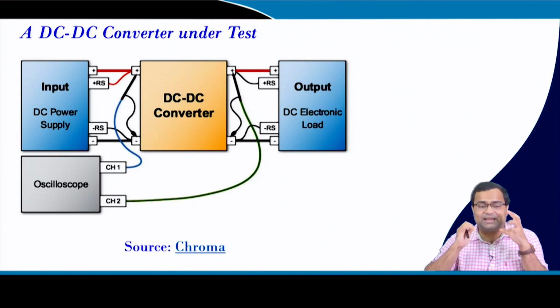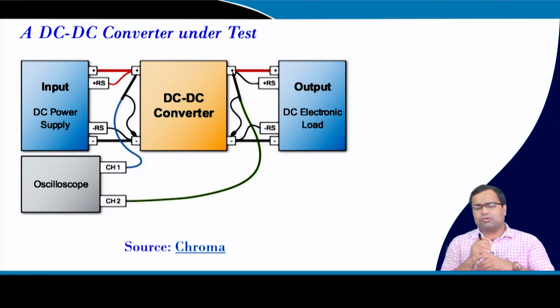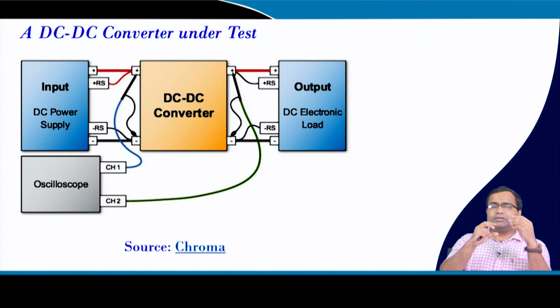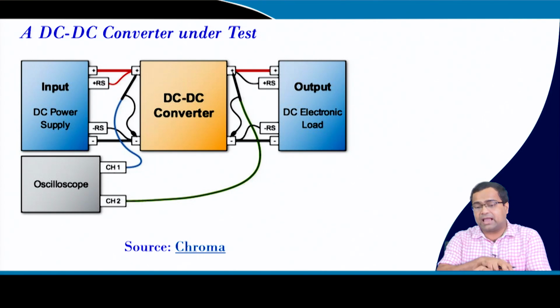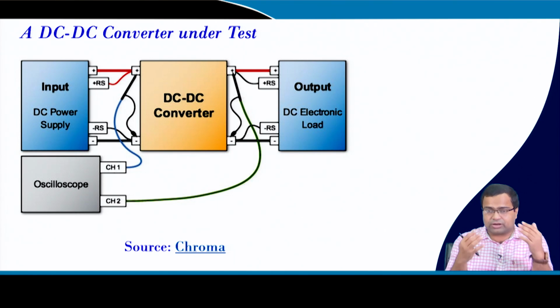where it is just a typical setup that we want to test a DC-DC converter, where the DC-DC converter can be a PMIC, where we can connect the external inductor and capacitor, but the PMIC will have its own controller, its own switches, and we need to evaluate the performance of that IC. That means, what is its load transient performance and so on, what are the control logic.